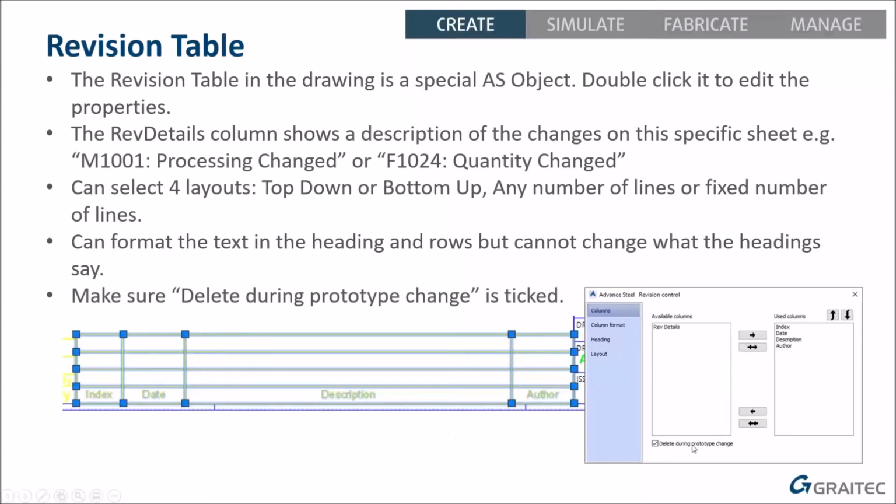There is a tick box here, delete during prototype change. It's a good idea to tick that, although changing the prototype after the drawing's created is not ideal. If you have to do it now and then, you want this to be deleted and replaced with a new one from the new prototype, or you end up with 2 or 3 on there. So make sure that's ticked.